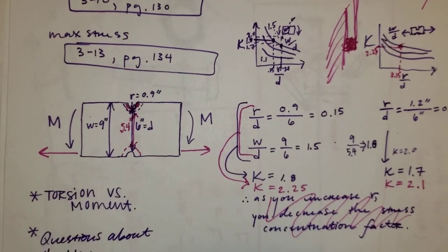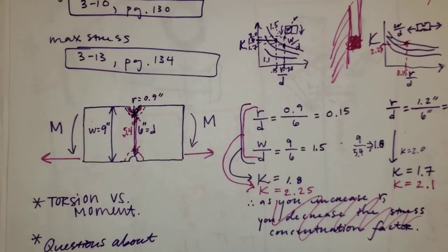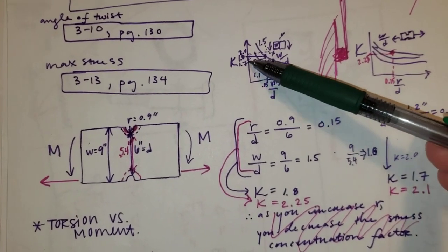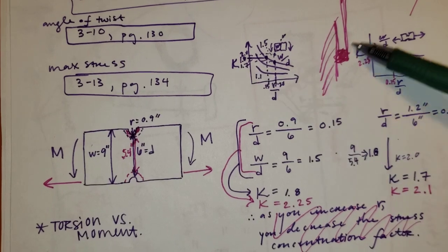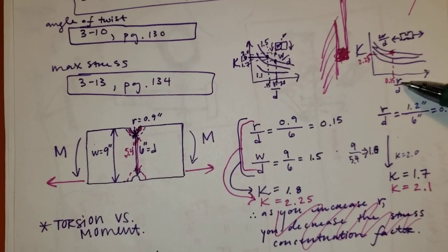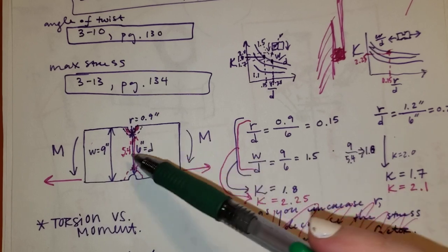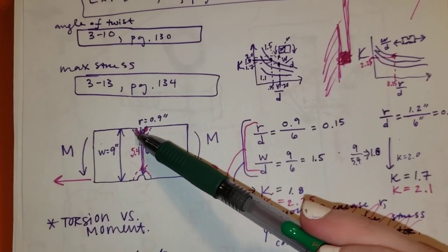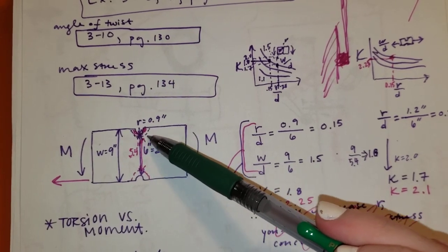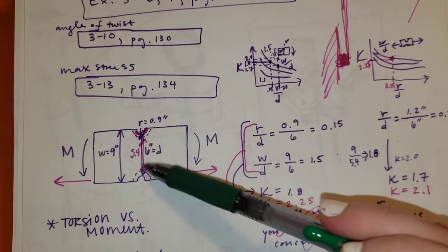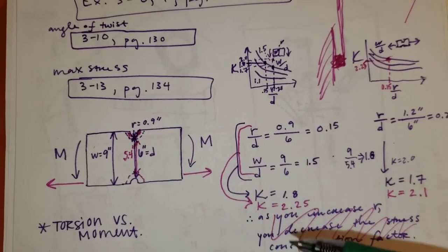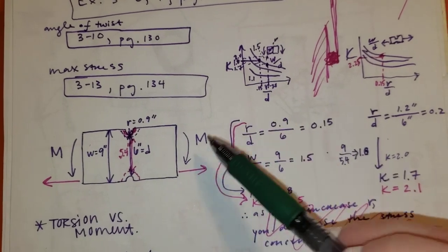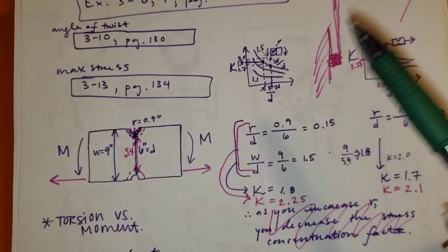like in Shigley's machine design book, you have in the appendix some tables that look a little bit like this. You have your stress concentration value, and you have this ratio. Now, this ratio is based on, okay, you have a little divot here, and there's some stress that's concentrated in this piece of metal. Or even the shape, we'll say.